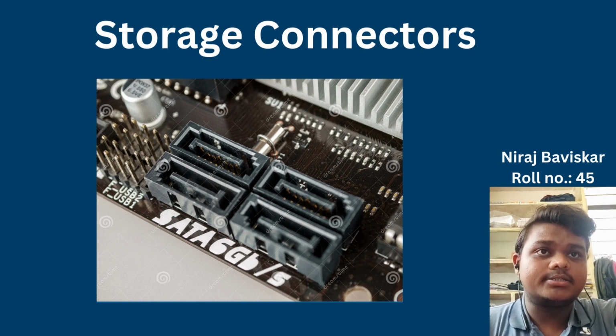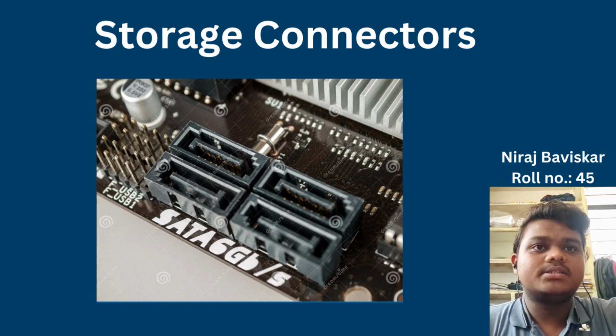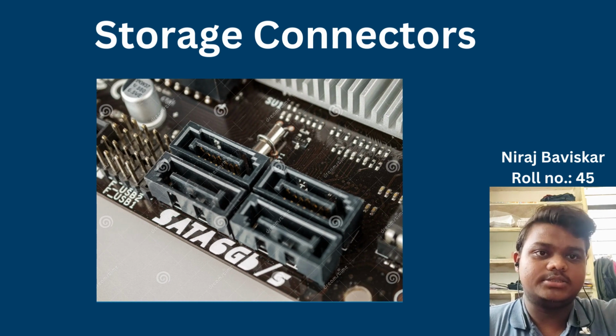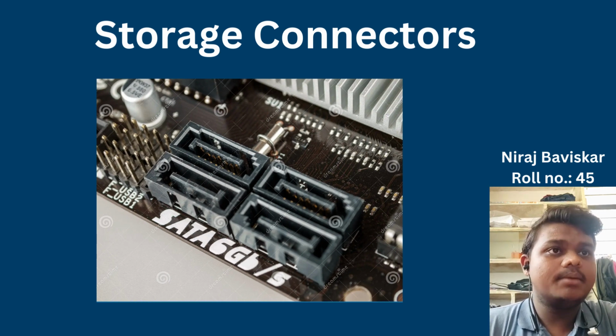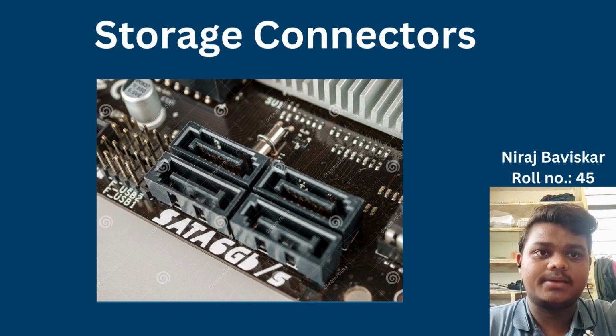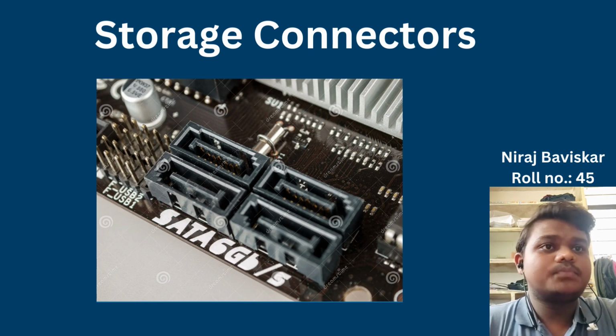First one, SATA connectors. SATA connectors have been the standard for connecting storage devices for many years. These connectors feature a small rectangular shape with a series of metal pins or slots. They support the Serial ATA interface, which allows high-speed data transfer between the storage devices and the motherboard. SATA connectors typically come in two variations, SATA 2 and SATA 3. The latter offers faster data transfer speeds, making it ideal for SSDs and other high performance storage devices.